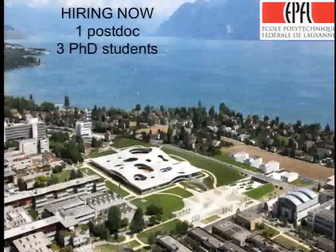Yes, in the video that we have shown, in the scientific paper, we put a magnetic compass and we simply let the robot go. And again, the concept here that what I really like is to trade the sophistication in the artificial intelligence and sensing with morphology. So instead of having a complicated sensor that can avoid the trees, we have a morphology that can absorb the collision, and all we need is simply a magnetic compass. We say, go north. In the product, we will have a remote operation because people want to be in control. And possibly we will have a video link so that you can always see with the camera within the inner frame where the robot is going.